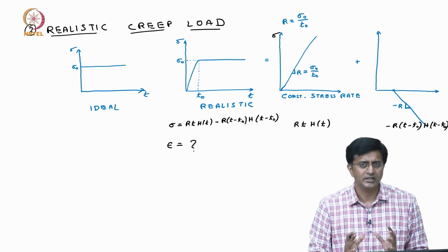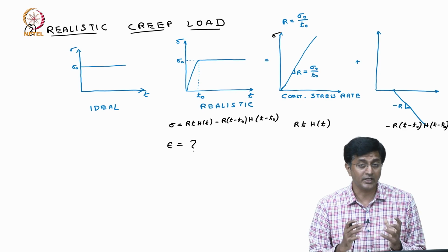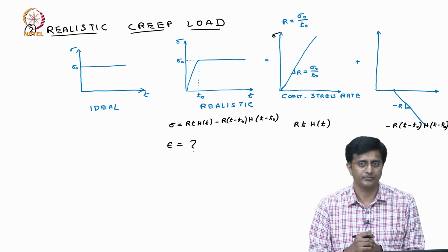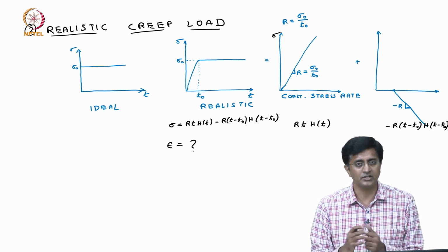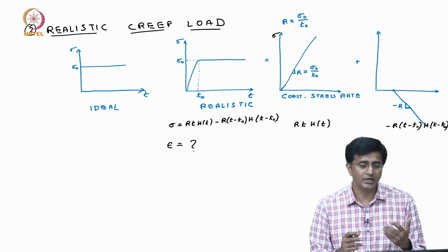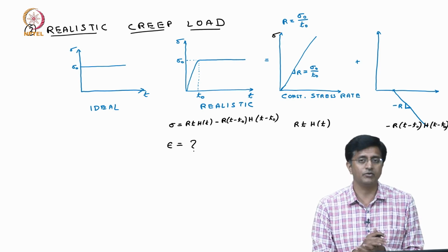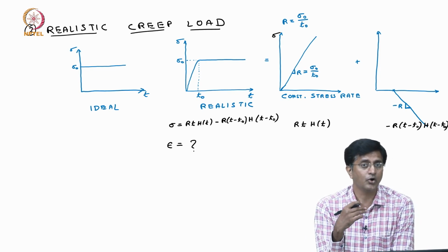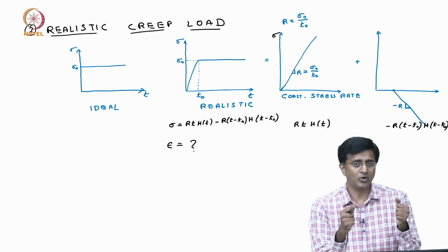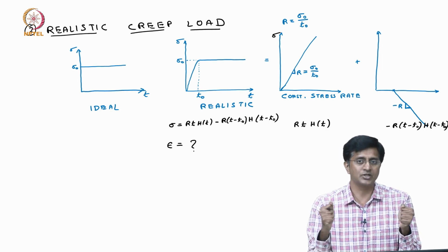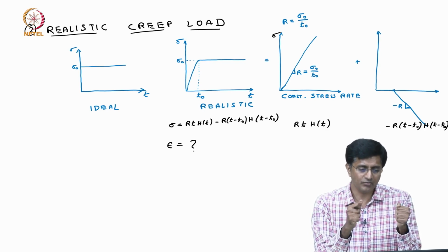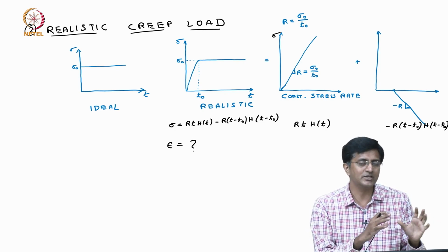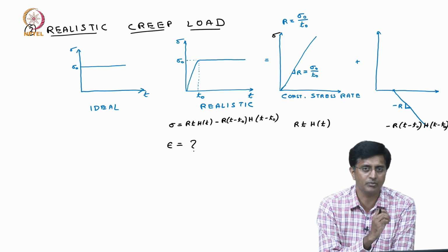To summarize, in this video we have shown you the derivation of how the stress and strain are related in a Kelvin model. So, once we got that stress strain relation, we used it to find what is the creep response of the Kelvin model. We have not shown you the response for the relaxation, but I hope you remember that for a Kelvin model it is not possible to apply a relaxation load, because we have the damper in parallel, we cannot apply an instantaneous displacement. That is the reason why we have not been discussing the relaxation load for the Kelvin model.